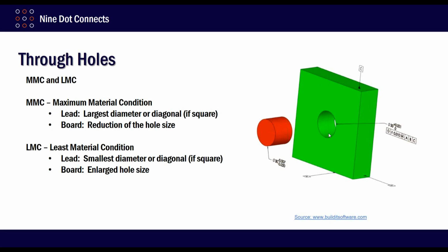And you can have two corner cases. One corner case is in which you have the pin at its largest diameter, and the maximum material for the board means that the hole is at its smallest diameter. And in some cases, if you don't do this right, the pin isn't going to go through the board even though it worked before. It's because there are just two different tolerances that are out of your control, one from the manufacturer and one from the fabricator.